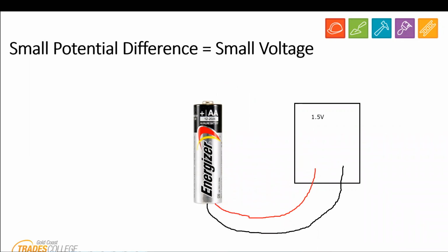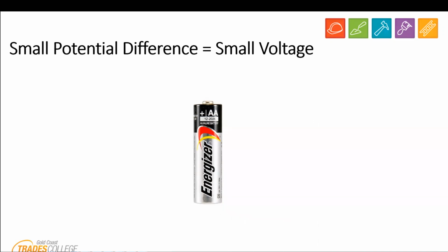Sometimes it's obvious to read the voltage of a battery, and suddenly when you open up an AC circuit, when you guys come to do that in the future, suddenly there's a lot of cables there, a lot of reds, a lot of greens, a lot of blacks. Suddenly it's very confusing. So we need to be able to understand that we're measuring from one point to the other. If you measure from one red to another red, you're going to see 0, because there's no difference there. Stupidly dangerous stuff.